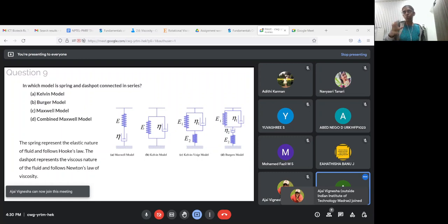Yeah, so it's actually all those kind of doors have a dashpot in it. So a dashpot is actually a unit that dampens the amount of force that you give. So you just forcefully open the door and you leave it open. It slowly starts to close instead of banging. So there is some kind of resistance that is happening to the door to prevent it from banging back to the wall. So this kind of resistance force is actually given by the dashpot. So when you apply a certain force to a dashpot, it tries to resist the force that you give.